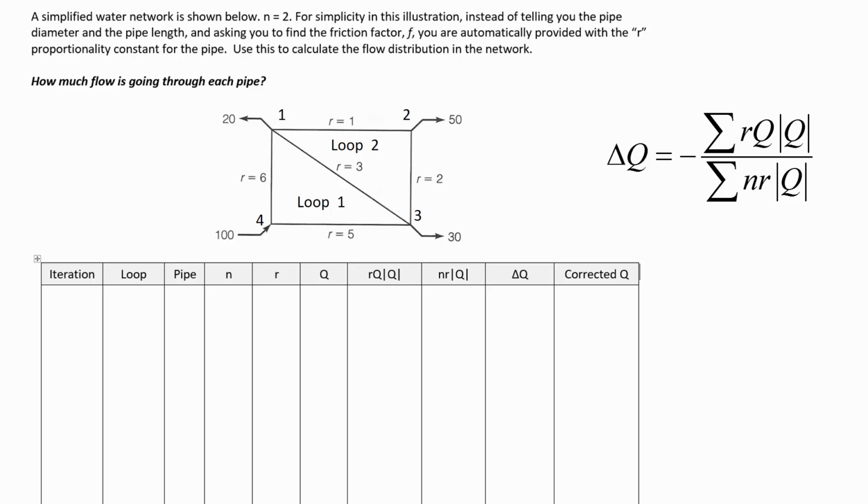What are we trying to converge? We're looking for these delta Q's to be so small that there's no reason to apply them anymore, meaning that the flow rates aren't changing from iteration to iteration. And when that happens, we're going to double check that the ins and the outs are equal at each junction. Great question. I'm glad you were asking. You're thinking in terms of when do we get to quit? Like what's the convergence criteria? Do we do this forever? No. We do it until the delta Q's are small enough that like 1% change is a good enough convergence. Are there other questions?